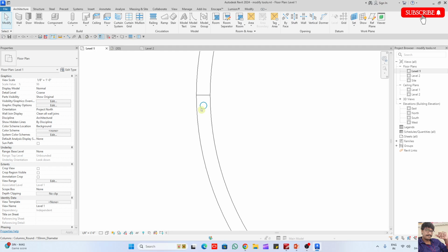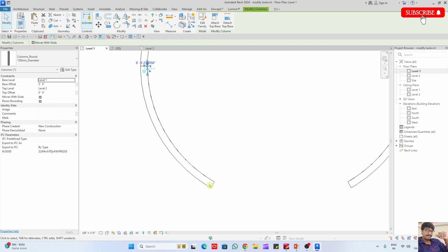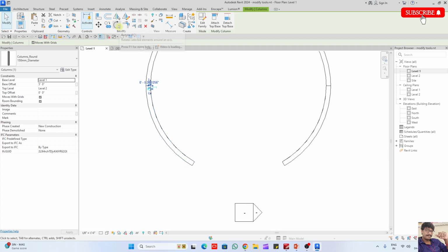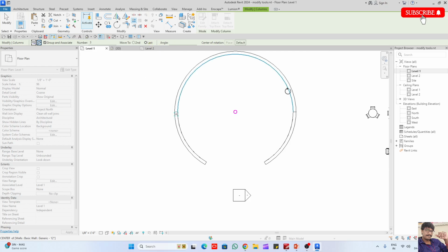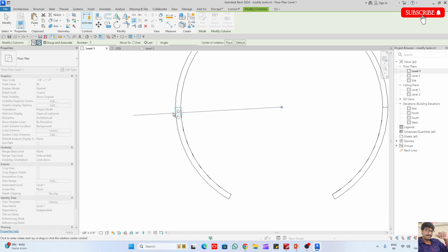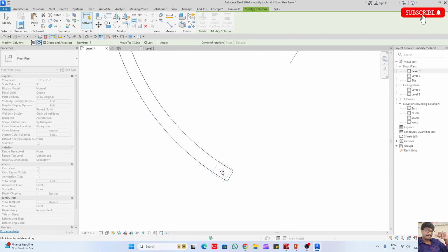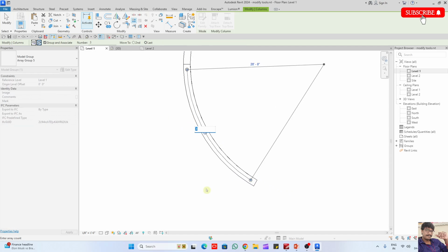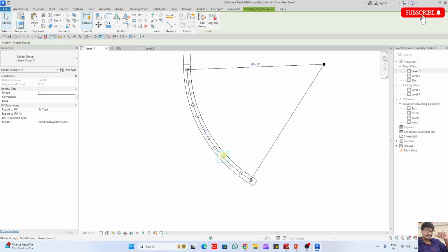Then you can see. Now select, this is the first angle and this is the last. Select object, polar array. Take the last, specify last angle around here. Give the count 10, 12. Select all.